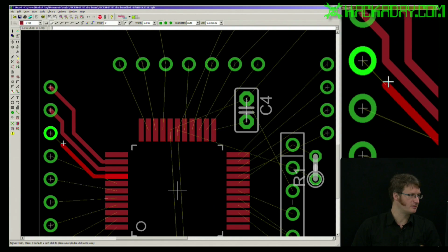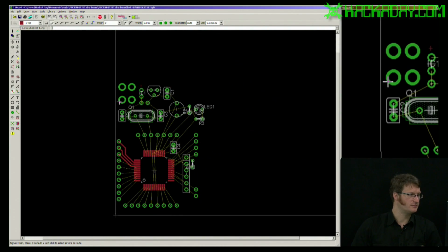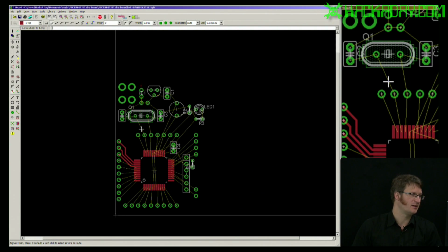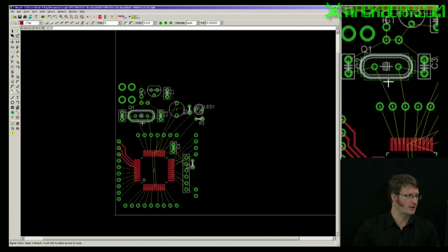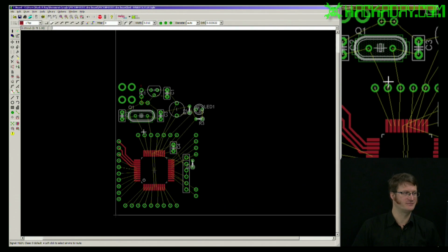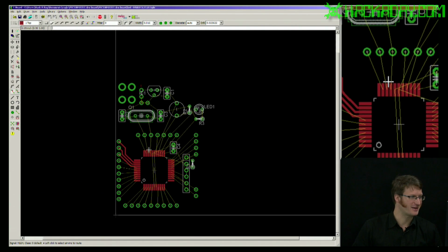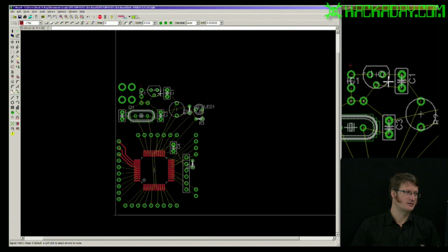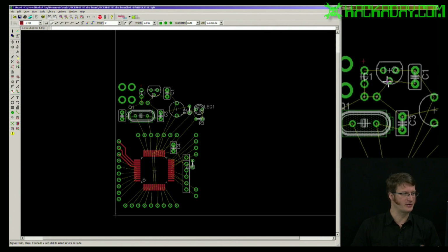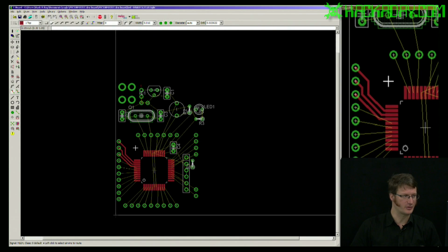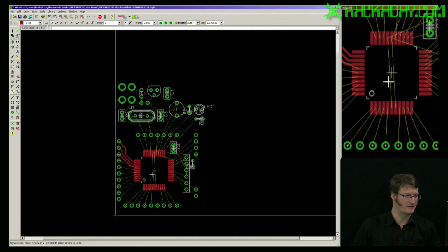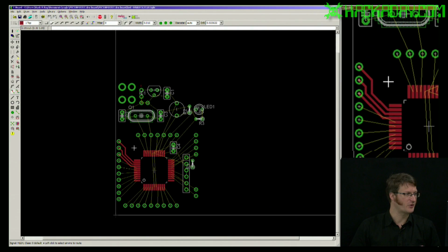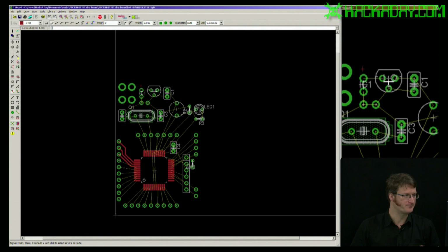So we'll just go along and do these. With your crystal, it's important to keep it relatively close to the processor so that it doesn't cause radio interference, and I don't know, people always say keep it close, so I keep it close. Also, your decoupling capacitor should be relatively close to the processor. Purists would say I need another one down here real close to the processor, but I have never found that to be an issue with PICs. They seem to be awfully tolerant processors, so I'm not going to do it. I'm just going to have it up by my voltage regulator.